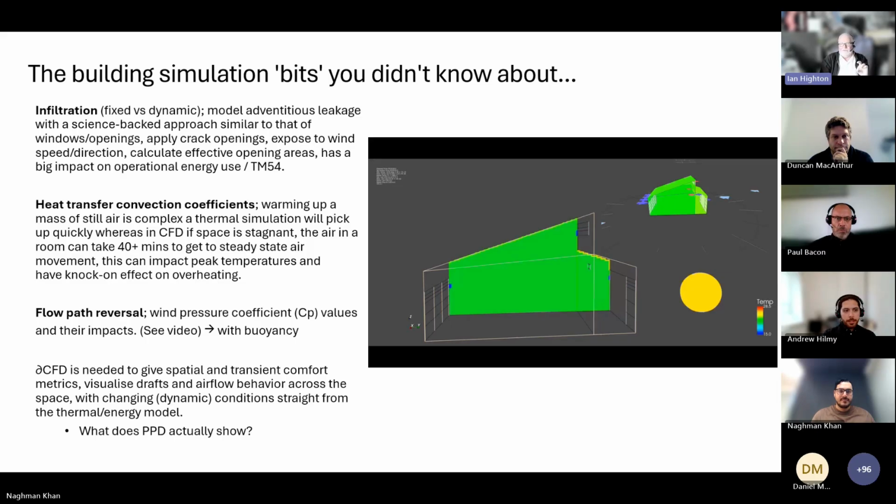The second one, which is less significant, is thermal bridging, edge losses, that kind of stuff. We obviously do the edge loss and the thermal bridging, but in real buildings the construction is usually far inferior to the perfection that is being put into the dynamic simulation models. I often say the DSM model is perfection. It's perfectly built, perfectly occupied, perfectly controlled, perfectly run.